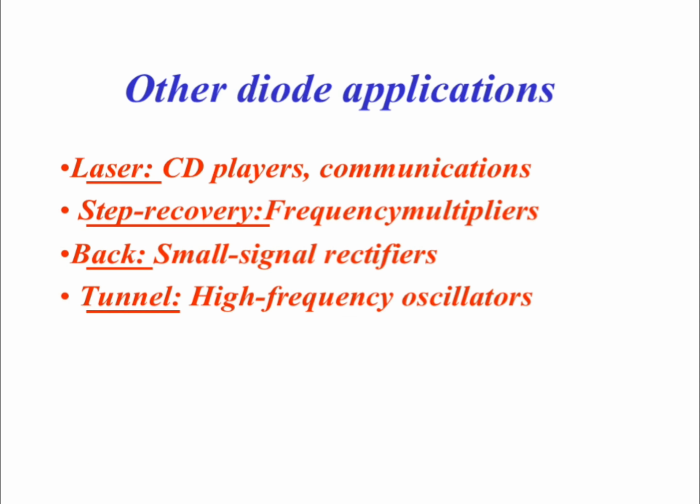Other diode applications. And these diode types have real applications. Lasers in CD players and communications, step recovery diodes in frequency multipliers, back diodes as small signal rectifiers, and tunnel diodes in high-frequency oscillators.